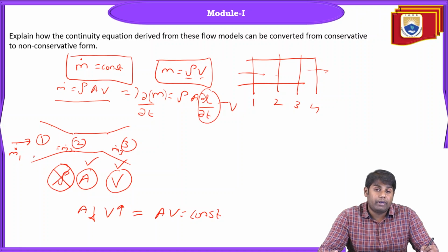When the flow is getting compressed, even the density will change, so density at each and every section will change. Now in the first section, it is converging. The area decreases, so the velocity should increase in this section. In the second section, the velocity will not vary, let's say it is constant, because the area is constant. When it enters the third section, the area is increasing, therefore the velocity will decrease. Then in the first section, when it is going through the convergent, the pressure will decrease.